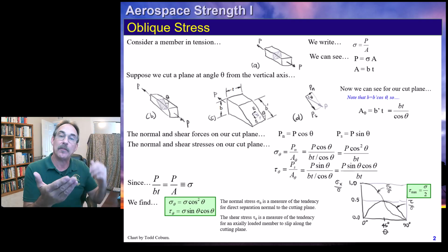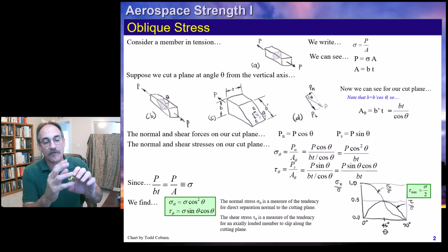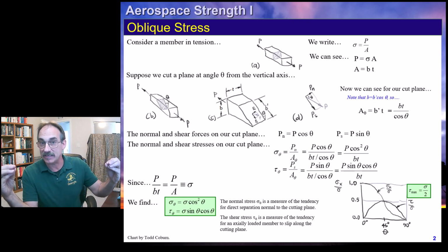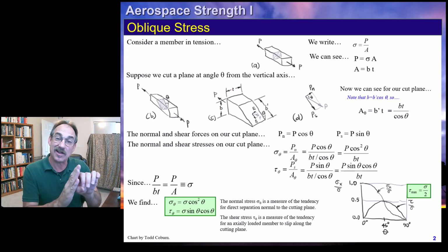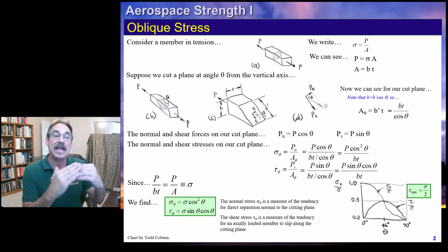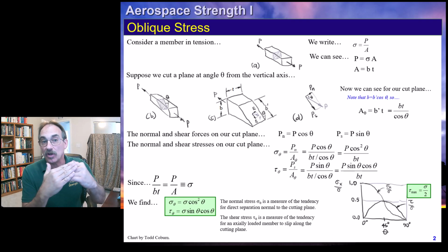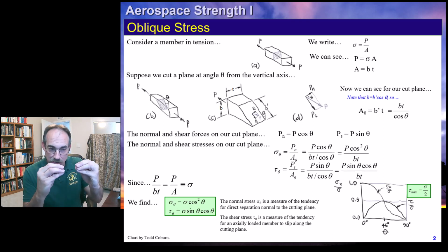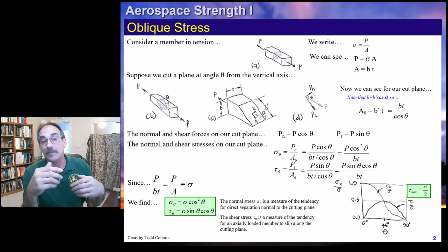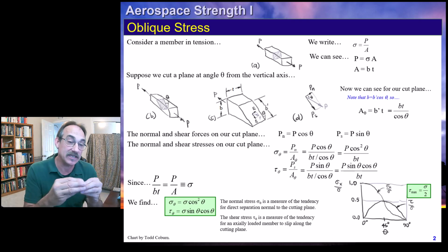So when we fail a part, a ductile material will often elongate and fail in tension, while a more brittle part will often not elongate a measurable amount, and you'll see a failure along these shear planes where the shear is maximum. If that part stretches, gets thinner and breaks, it looks like it stretched out and then broke, that would mean it's a ductile material and it failed in tension.